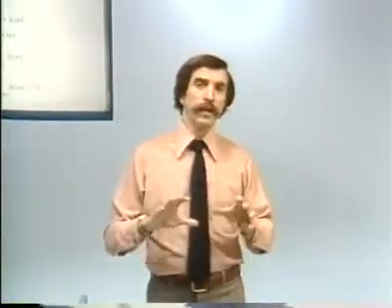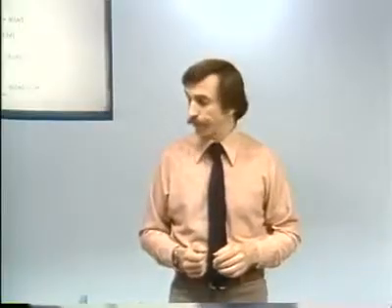But first, what I'd like to do is to continue to focus on the system function for linear time invariant systems and make a couple of comments that tie back to some things that we said in the last lecture relating to the relationship between the region of convergence of a Z-transform and where that is in relation to the poles of the Z-transform.